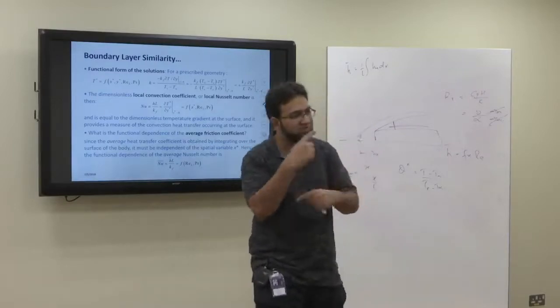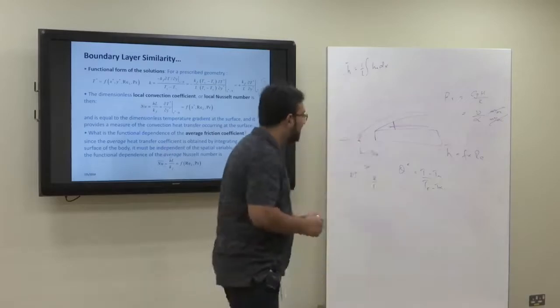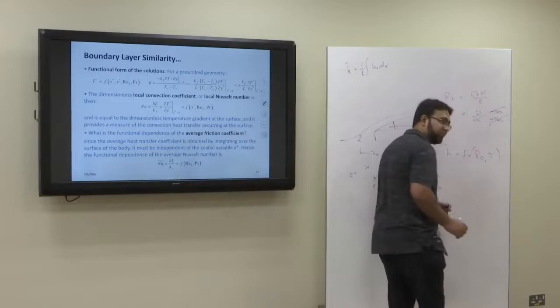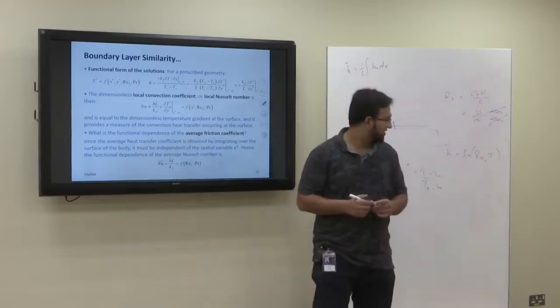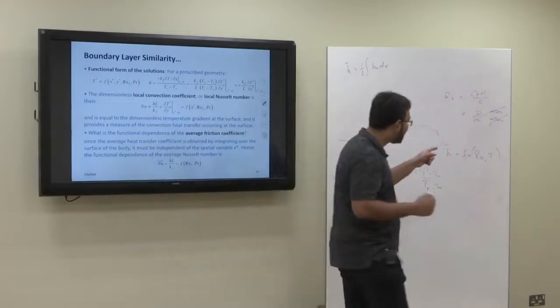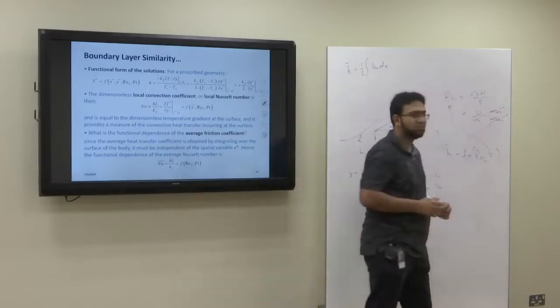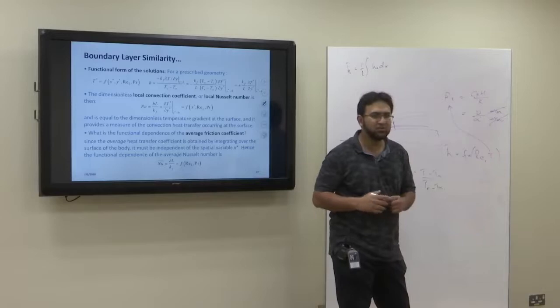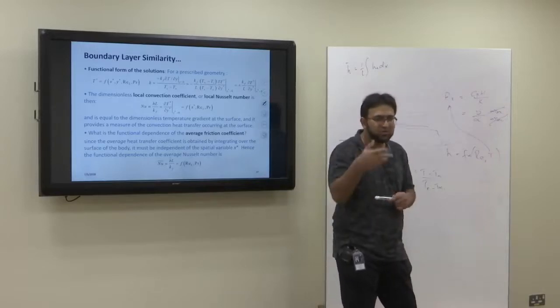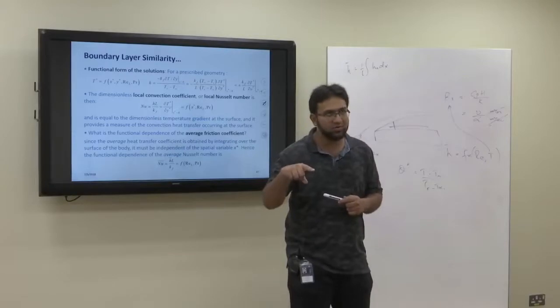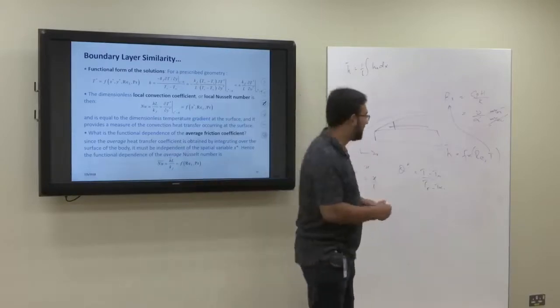So if we have different temperatures, we had different values of C, right? So we have T here as well. Temperature is also important for the heat transfer coefficient. Now for temperature, we can use the Prandtl number, because Prandtl number is hugely dependent upon temperature. So if temperature varies, Prandtl number varies. So basically, heat transfer coefficient depends upon Reynolds number and the Prandtl number. Okay?